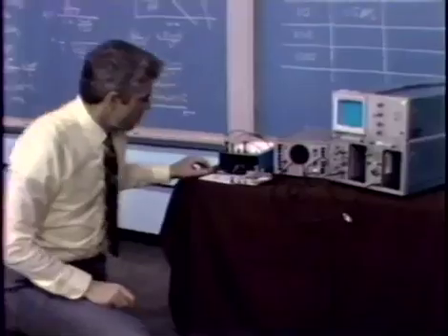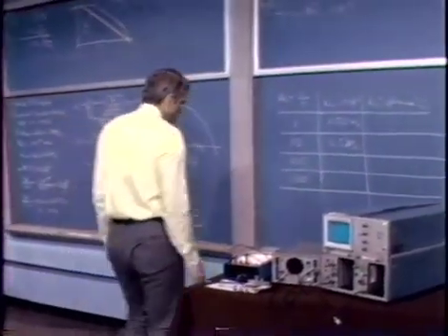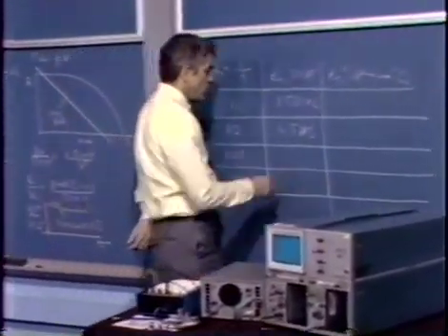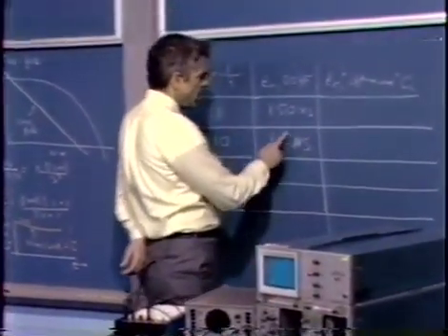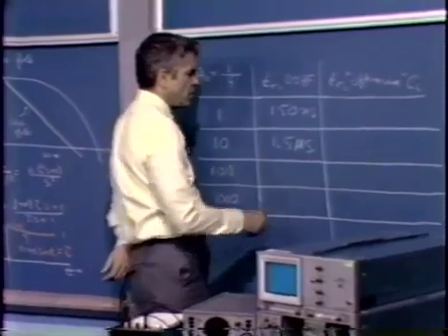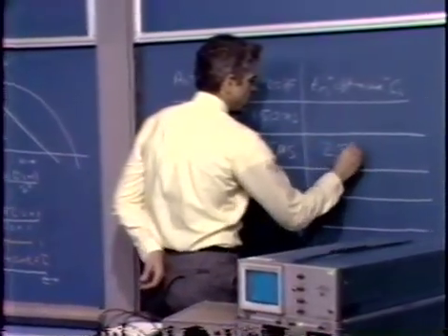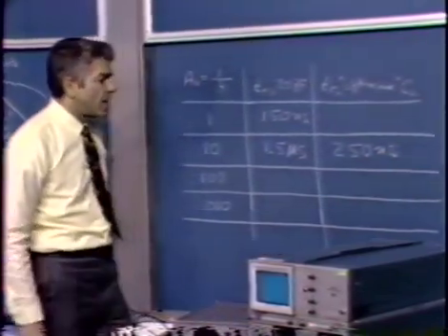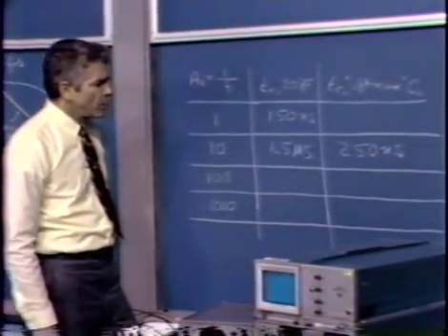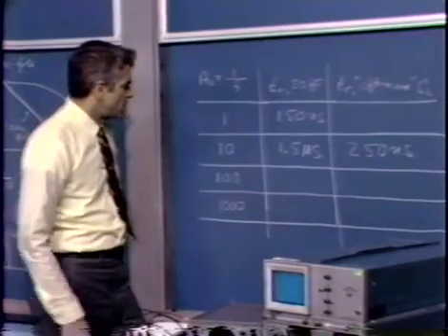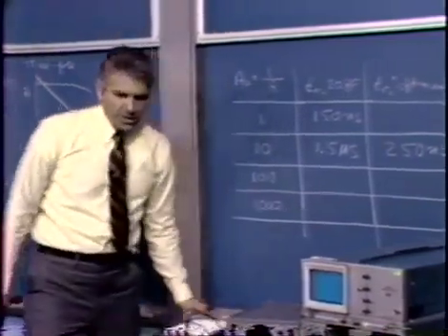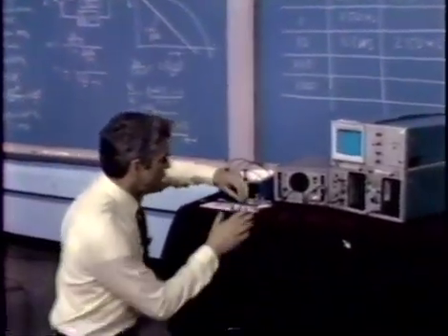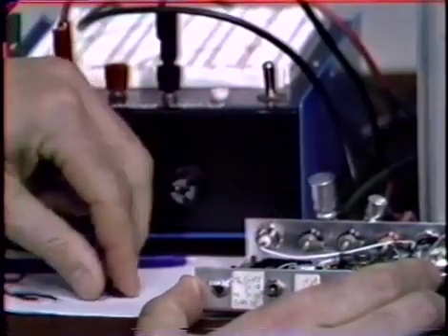And so we're able to, by choosing an appropriate capacitor, reduce the rise time, not quite to its original value, but we get about 250 nanoseconds. So rather than losing a factor of 10 to 1 in bandwidth or rise time, we've lost a factor of maybe 6 to 1. Well, let's continue. Let's first of all go back to the original 20 picofarad capacitor.